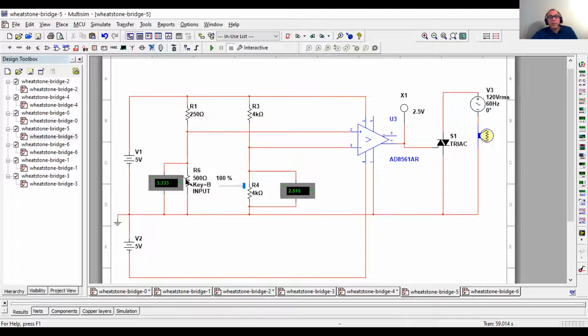So this is going to simulate a photoresistor. And a photoresistor, as it gets darker, the resistance goes up, okay? So what happens now is, on a photoresistor, right now it's the middle of the day, voltage is 0, so negative is greater than positive input on the comparator, which means we have a 0, so nothing's happening here. So it's still light out, so we do not need this light to be activated outside.